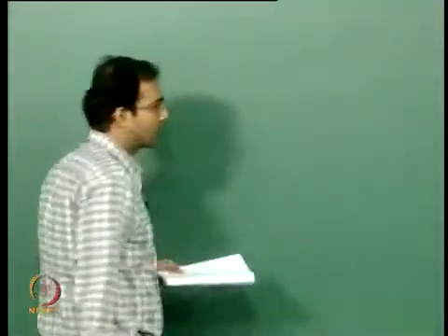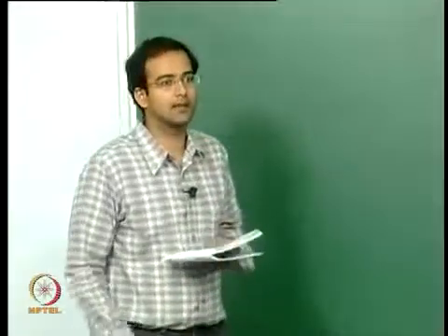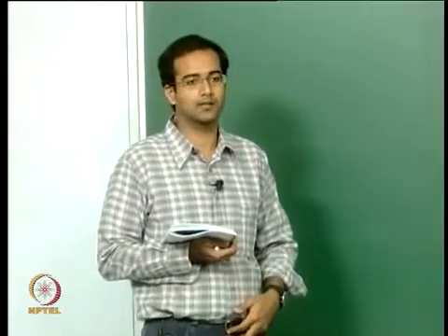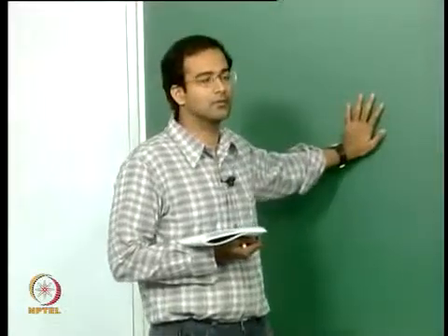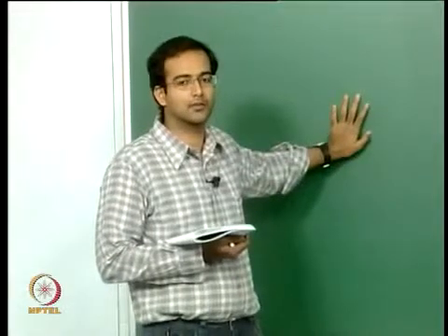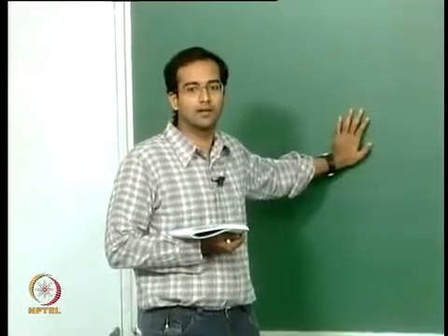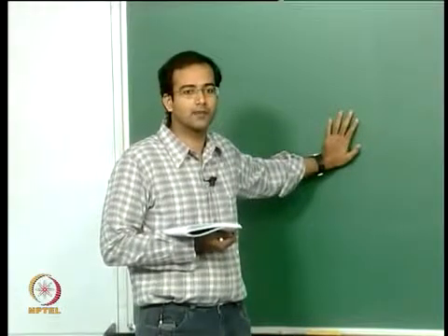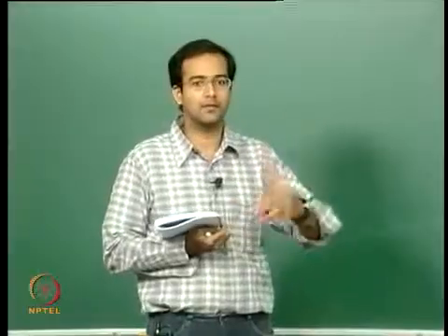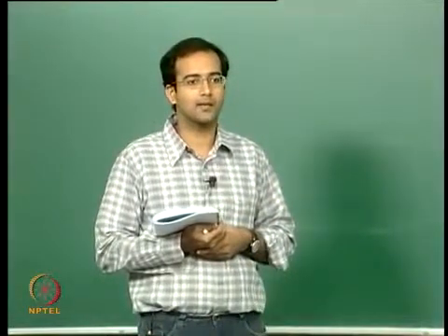Therefore we will start looking at some basic aspects of internal flows before going into the mathematical theory of how to solve laminar internal flow heat transfer. I think most of you are familiar with the basics of internal flows from your fluid mechanics classes and your earlier heat transfer class. So I am going to give a very brief overview, and we will look at the basic fully developed case first, where we can get the solution for velocity profiles very easily, and then we will gradually go to the case where we have heat transfer. So we will look at different regions again. First we will start with the simplest case, that is both hydrodynamically and thermally fully developed.